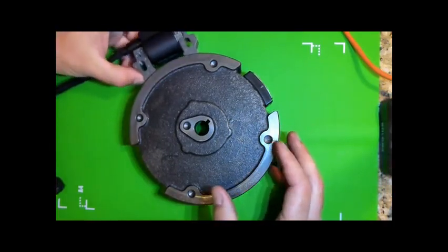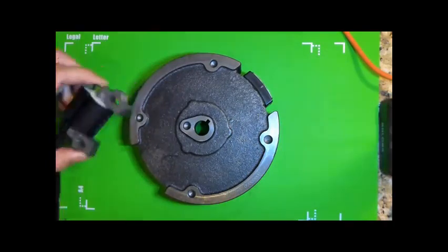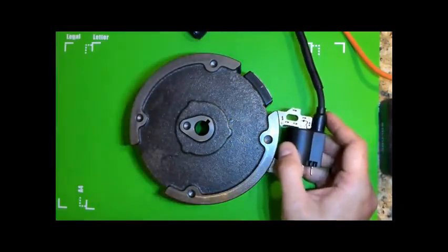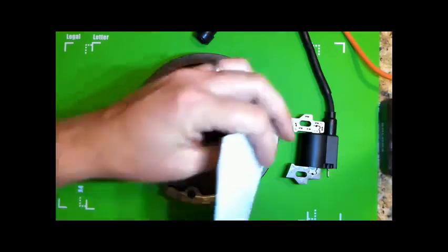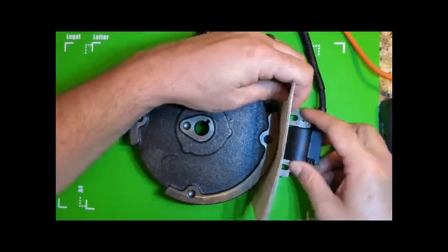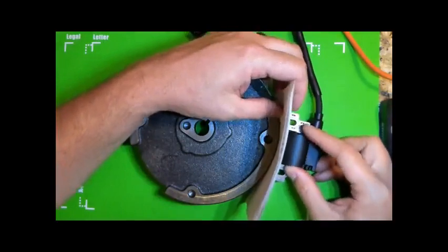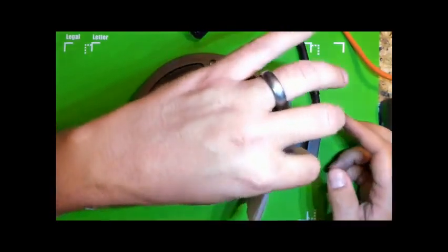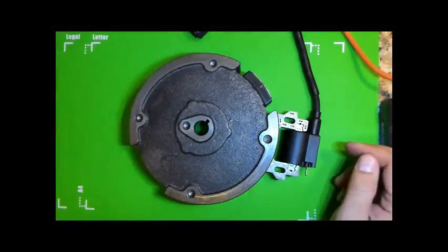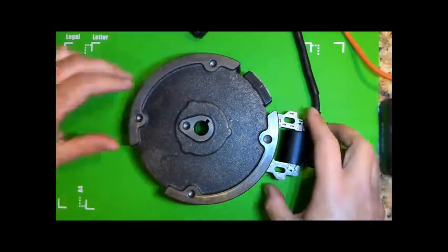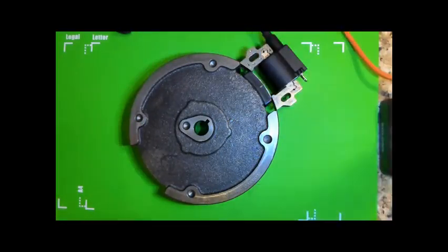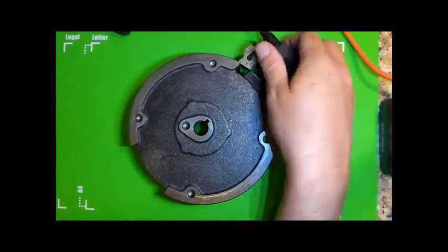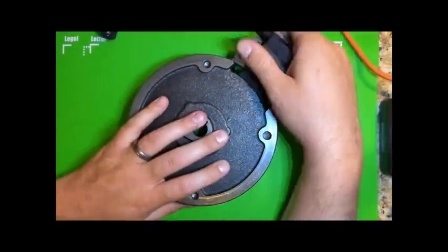The armature is going to ride very, very close to the flywheel. We're talking about the thickness of an index card or a folded over piece of notebook paper that we can actually use to set our armature air gap. If I do that, and I'll try to remove this paper, you can see that from your angle it actually looks like it's touching, but it would actually be able to spin. We don't want it touching, because when we get too close to the magnet, it's rather strong, and now we couldn't rotate it with our recoil starter.